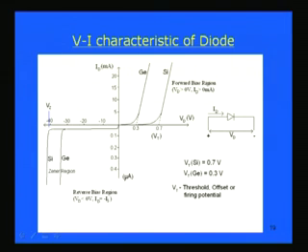The power dissipation capability of the diode must be very high. With normal diodes, if we apply a very high reverse bias potential, the diode may not be able to sustain that high power being dissipated. So you generally do not apply such a high potential to a normal diode, and for that purpose Zener diodes are used, which can withstand this high power.